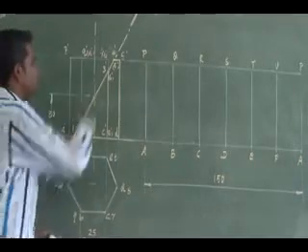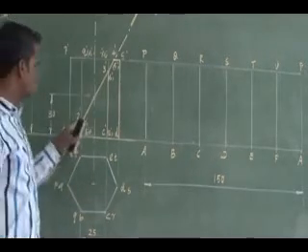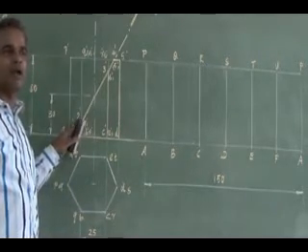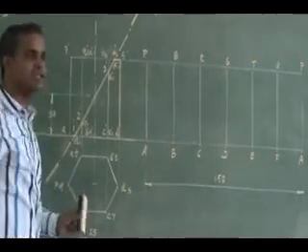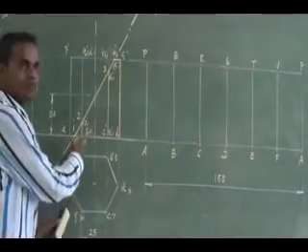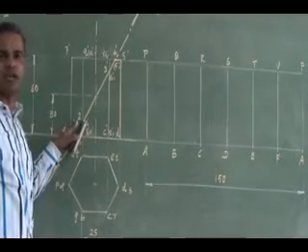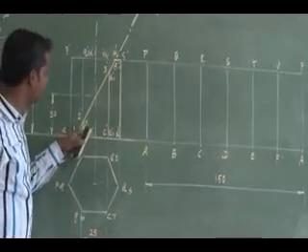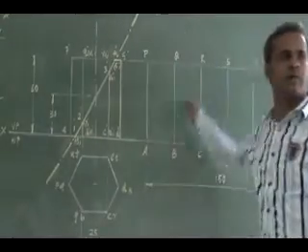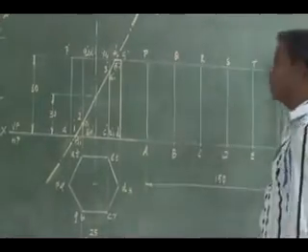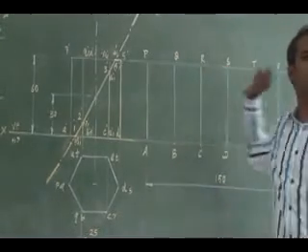So you see here, first of all, I will come back to this base cutting point. Listen. So you look at this vertical edge cutting point. That is cutting point 2. Cutting point 2 is on which visible edge? Visible BQ. Right? It is at BQ. Cutting point 2 is at BQ. Similarly, 7 is at FU. So you see here, BQ I have in my development here, FU I have here. Somewhere on those I have to mark exactly cutting points 2 and 7.